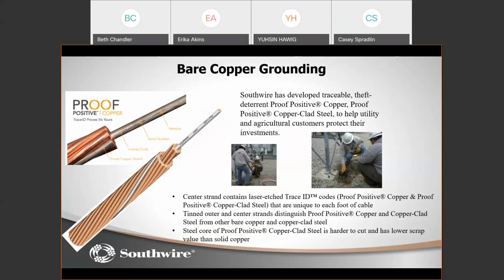And another question, still related to the jacketing compound: do we have a flame test result or passing flame tests for those compounds? The answer is no. For all the polyolefin polymer family, which is polyethylene-based, polypropylene, LLDPE, high-density polyethylene, or cross-linked polyethylene, those polyolefin-based jacketing compounds do not have any flame retardant additive.